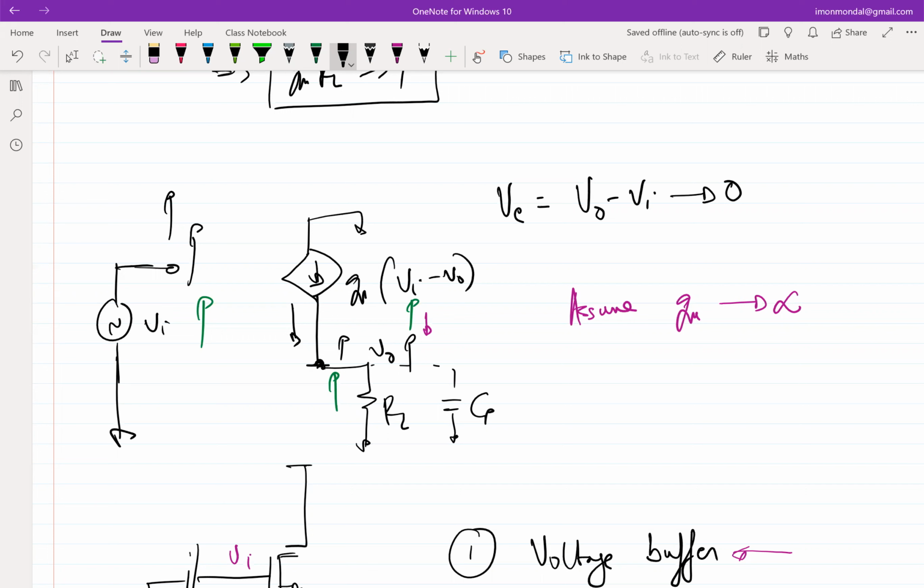Right. So there was a midterm question also where I think I may ask what happens if something goes to infinity. Yes, right. You will see that your output actually settles to some value. But there was one tutorial question also where I asked, when y21 goes to infinity, what happens? These are related, and you have done this in a different context. You have done ideal op amps in ESC 201. In ideal op amps, when you set A to be infinity, you have this virtual ground that appears.